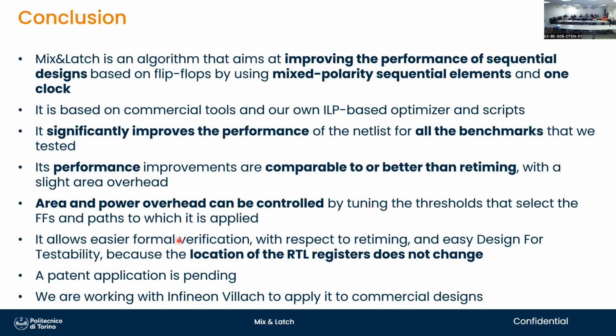In conclusion, we have shown how to use all 4 sequential memory elements that you learned exist in digital design nature. Previously, you could use only 1 or 2 of them. We use all 4, and we use that to improve performance significantly on a fairly non-trivial design like a RISC-V core. We achieved 50% performance improvement, which is better than retiming and allows formal verification to be used without any problems.